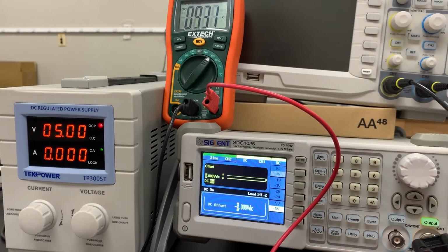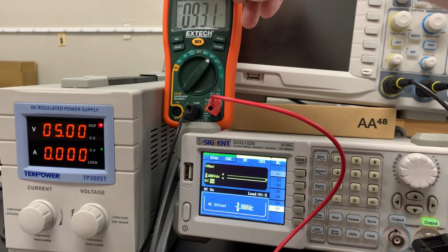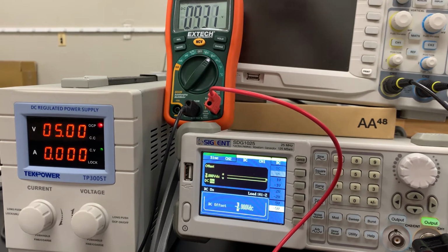Once the schematic has been made, we're then asked to measure the voltage across R5. When we measure it, you'll see that it's 9.31 volts. And we can use this to find our reference current by using Ohm's law, where V equals IR, and R is the measured resistance that I mentioned earlier.